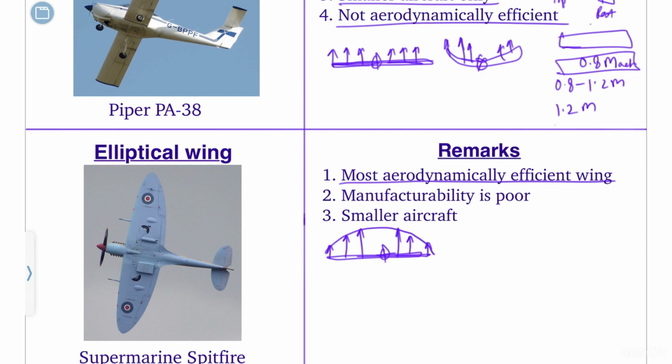of lift. The bending issue of the wing does not come into play, and also the vortex generation, because at the tip of the wing, because of the low and high pressure below and above the wing, the vortex generation which is happening does not affect much of the lift. So that's why these are the most efficient wings in the complete wing structure.